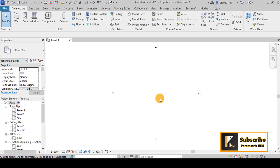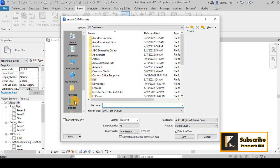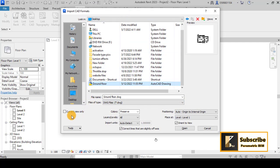Now once I am in Revit, I will go to Insert, and then Import CAD, and choose my ground floor file that I have saved. You have this window, so click here for current view only, and for the colors, I always prefer to have black and white. You have the opportunity to preserve the layers if you have layers, or invert them to other colors, but I will choose black and white.